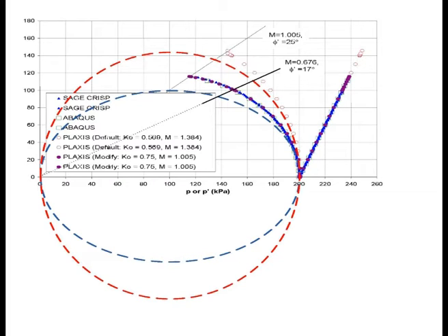And so a lot of people came to the conclusion that it will behave just like Cam Clay, right? But it doesn't behave like Cam Clay. Let me just revise how the Cam Clay model is put together. The blue ellipse basically shows the Cam Clay, and this angle of friction, which is deemed to be the critical state angle of friction, passes through the crown of the ellipse. Is that alright? That is for Cam Clay.